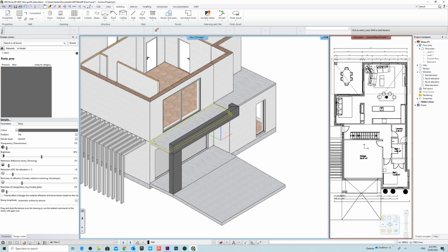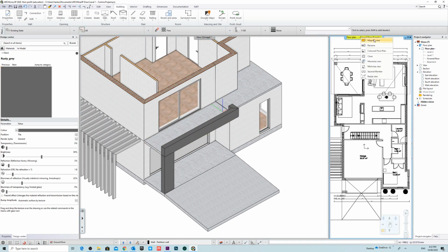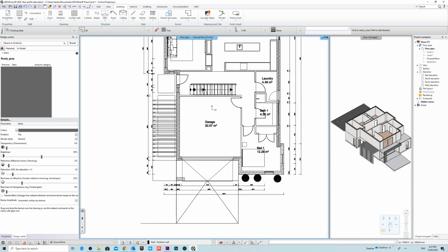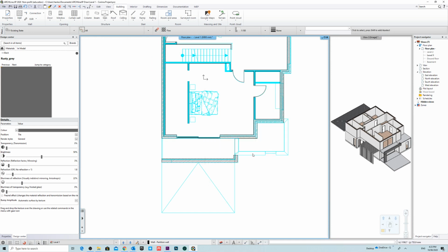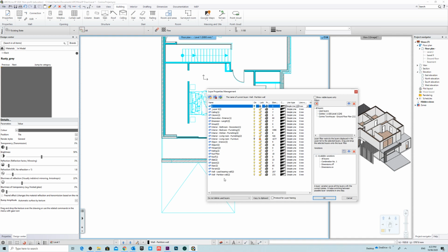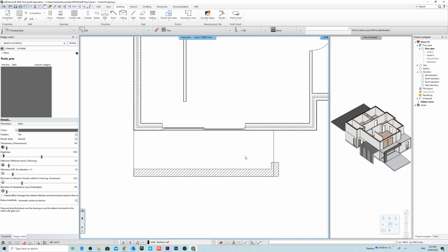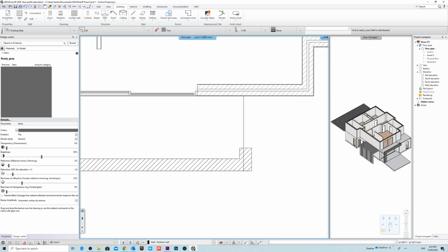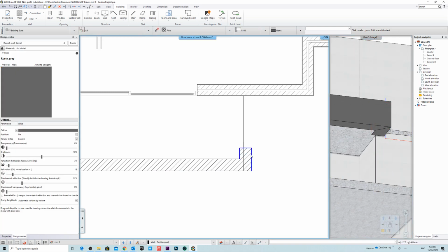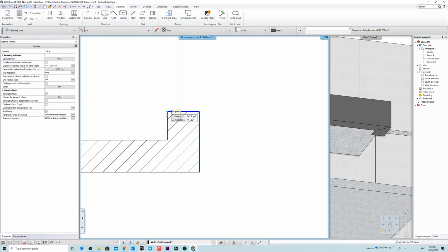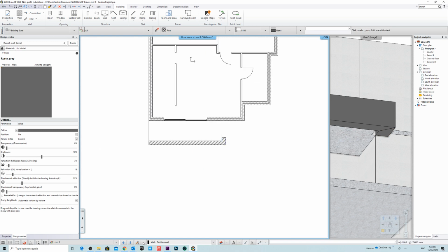Okay, and I'm just going to create basically the railing over here. Okay, and we're just going to create a really nice simple railing. So let's go up. Okay, I'm going to just hide the DWG again, like that. And like this. Okay, first of all, this needs to go right to the side. So we can just make that adjustment. Just move this like that. Okay. So we just rebuild it.